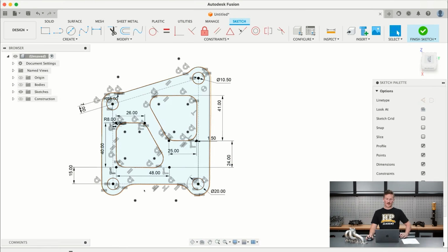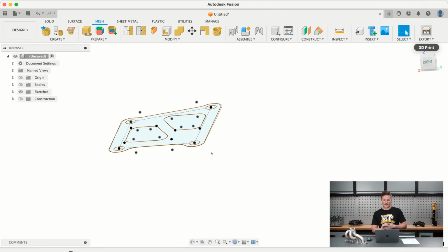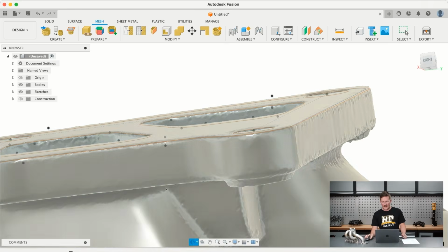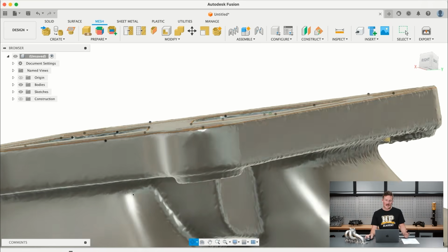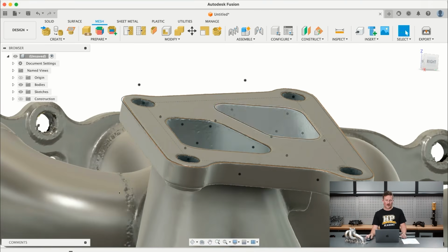Now we've got a fully defined sketch for our flange profile. So we'll just hit OK with that. And one thing to remember is that compared to the surface, the actual sketch flange there was exactly 0.5 millimeter further down. As we created that mesh section sketch, we dropped it down to get a clear profile there.